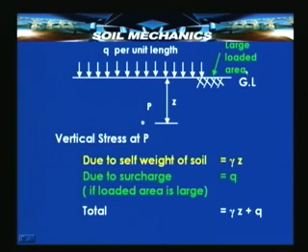But if the loaded area is large, we can safely take the surcharge or the stress due to the surcharge as Q at depth Z as well, which means at depth Z the total stress is going to be gamma Z plus Q. But what are we interested in?